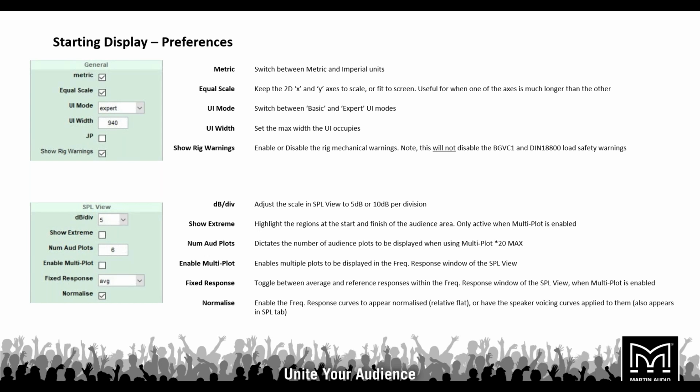But for that reason, the design may include an angle that is not achievable with our rigging brackets or frames, but it's something that you can achieve with one of those solutions. So you can just turn that off, because the last thing you want is to get a printable report that says fail to show a customer and have to explain, no, this just fails because we're doing a custom solution. So you can disable that there.